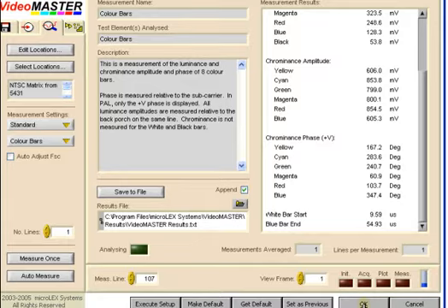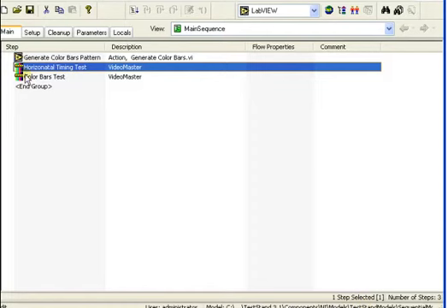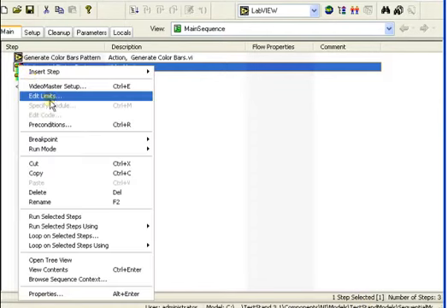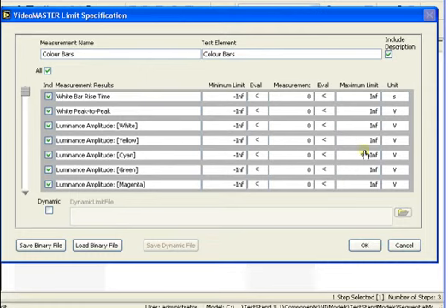With these tests defined and created, I can then go back to the TestStand product and create limits. In automating my test, I'm going to want to define what constitutes a pass or a fail. TestStand allows me to easily define, for each of the information passed back from a configurable TestStand step type, what is acceptable and what is not.